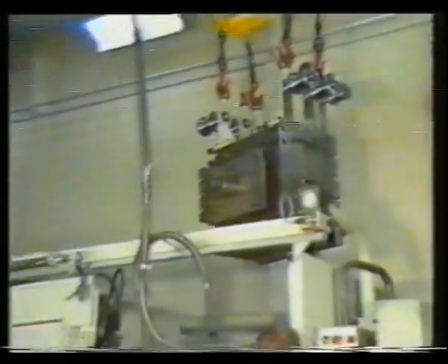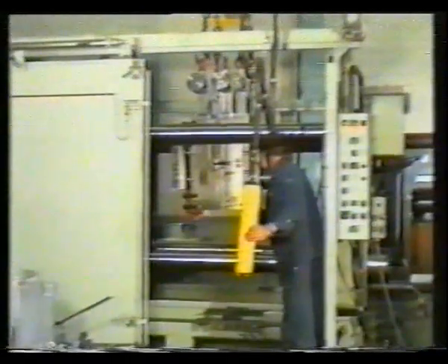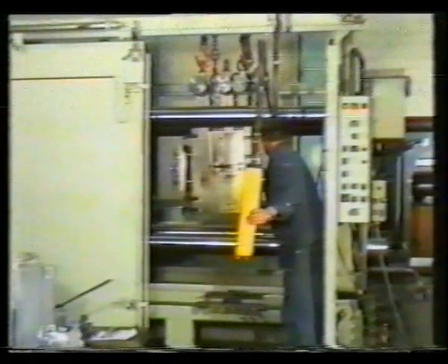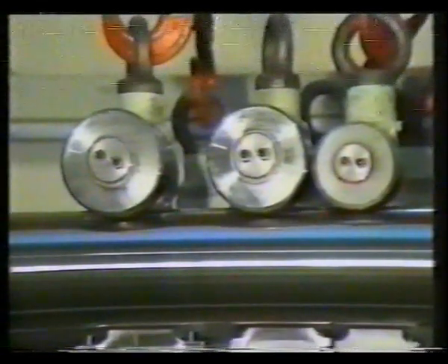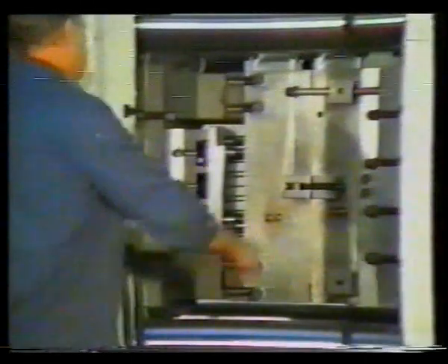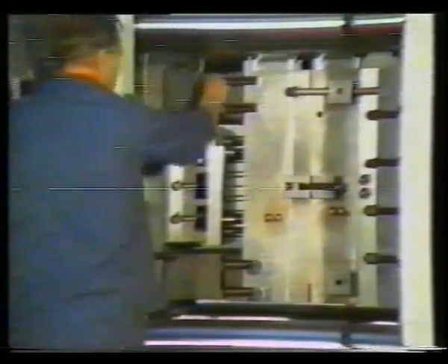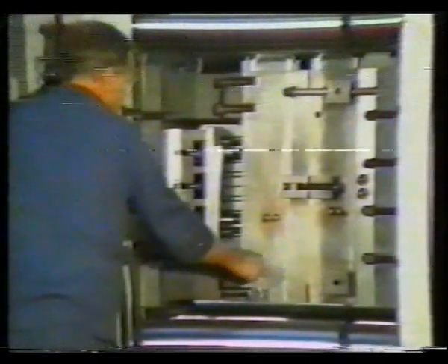All of the dies used can be coupled to the machine-integrated base. The next die for bearing plates, already preheated, can now pass between the tie bars, centering itself by means of its support rollers. Hinged bolts and latches at the partition line allow production to be continued after a short time.